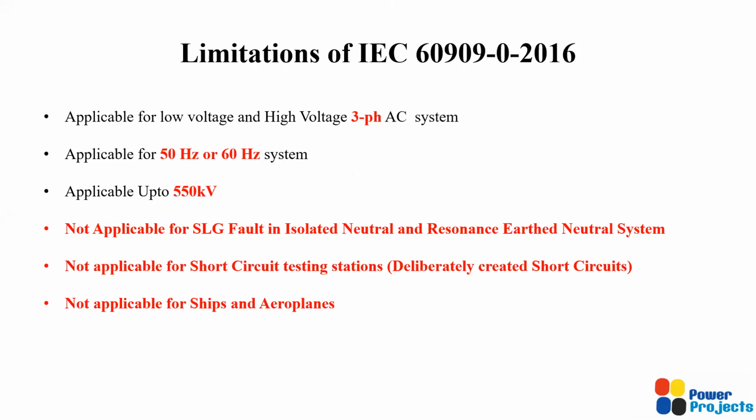It is applicable only for 50 Hertz and 60 Hertz, which means, again, it will not be suitable for DC, or even for other frequencies in special applications like 400 Hertz or 16.7 Hertz. And this is applicable only up to 550 kV, and there could be some special measures which are needed above 550 kV. Okay, and the serious limitations or constraints of this IEC come at the last 3 points.